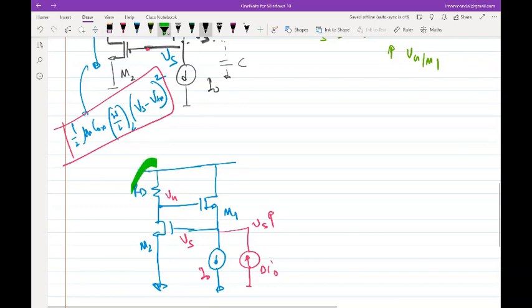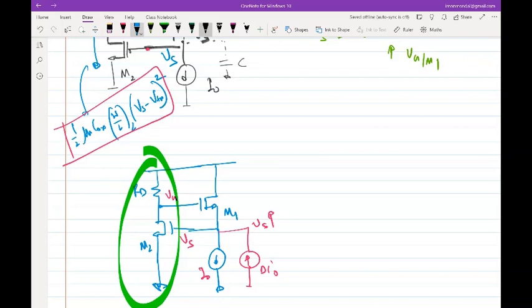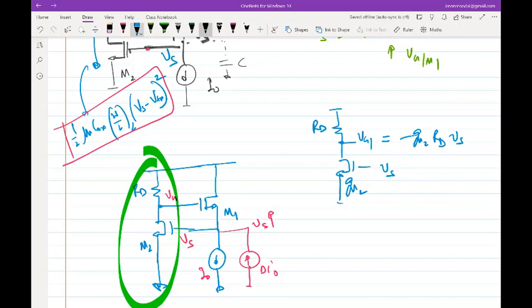So this stuff over here, you can just forget about the stuff that is connected. If this is VS, this is VG of M1. So what will be the incremental relationship between VS and VG1? This will be not approximately, but exactly equal to minus Gm2 RD times VS, assuming M2 is in saturation, and that's what we argued, that this will be in saturation. Does that make sense?